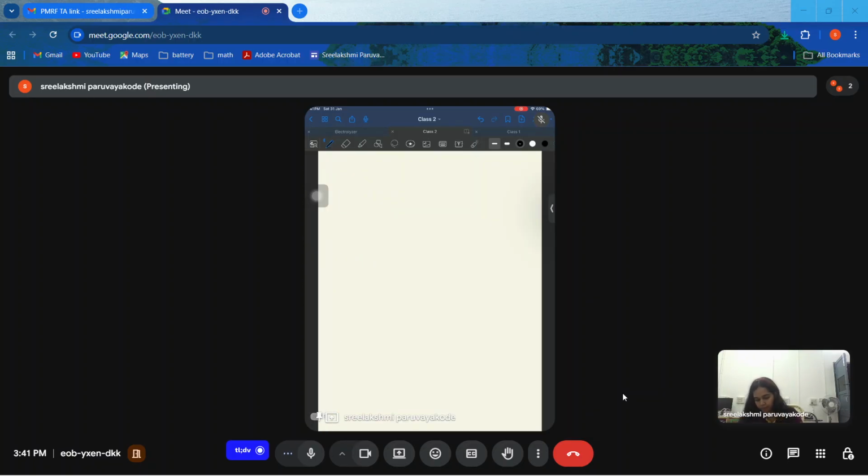I'll write this down again. Z total equal to 20 plus 1 by j omega 10 into 10 to the power minus 6 plus 1 by 100. Now I'm going to multiply everything by 100. That is 20 plus 100 by j omega 100 into 10 into 10 to the power minus 6, which is 10 to the power minus 3, plus 1. Now, what is this in the form? This is a plus jb.